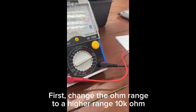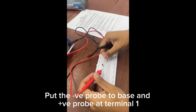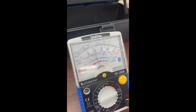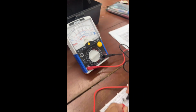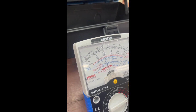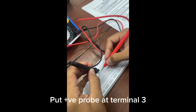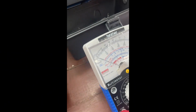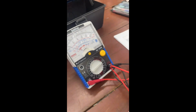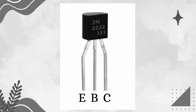First, change the ohm range to a higher range, 10k ohm. Next, put the negative probe to the base and the positive probe at terminal 1. The scale is low. And then, put the positive probe at terminal 3. The scale is infinity. So, this is the result.